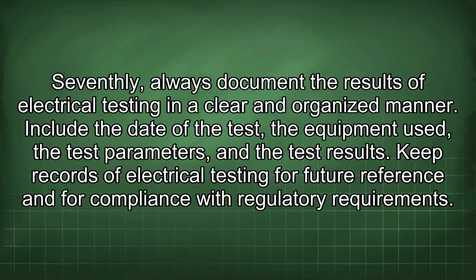Seventhly, always document the results of electrical testing in a clear and organized manner. Include the date of the test, the equipment used, the test parameters, and the test results. Keep records of electrical testing for future reference and for compliance with regulatory requirements.